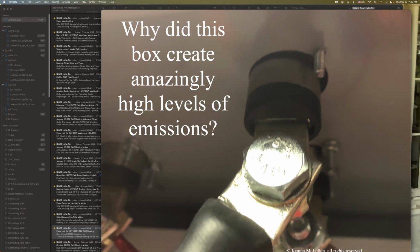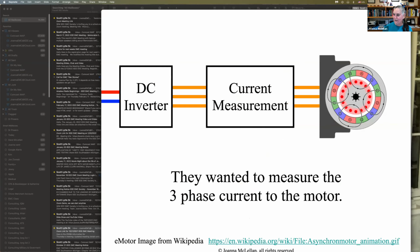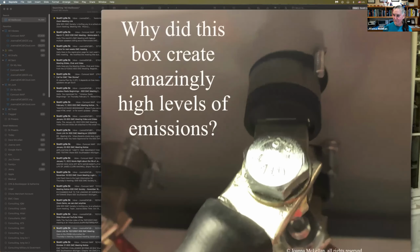Is this, at least in the picture, an enclosed metal box, or is this just exposed to the open atmosphere? This was just a big metal box with a bunch of orange cables coming up to it. 3 orange cables on one side, 3 orange cables on the other side, and a way to measure the current on the inside. The way they built the box, where the shield of the orange cable was not properly mounted to the box, caused the problem. There was RF current going back on the outside of the shield.